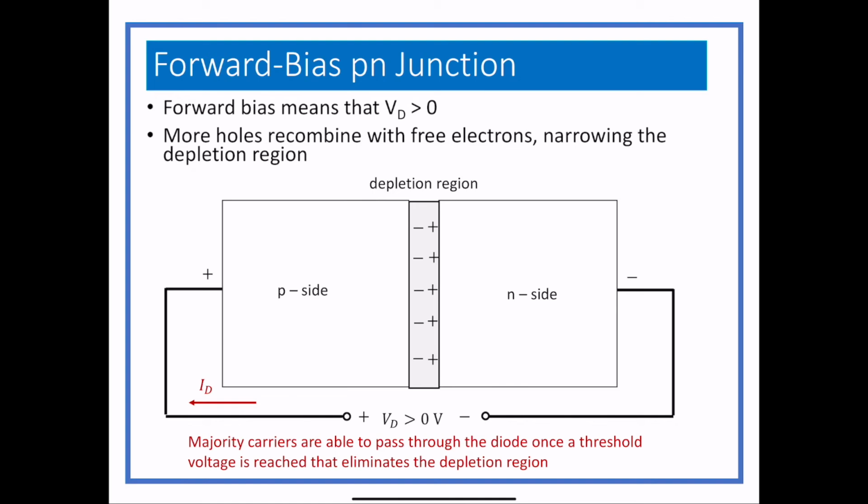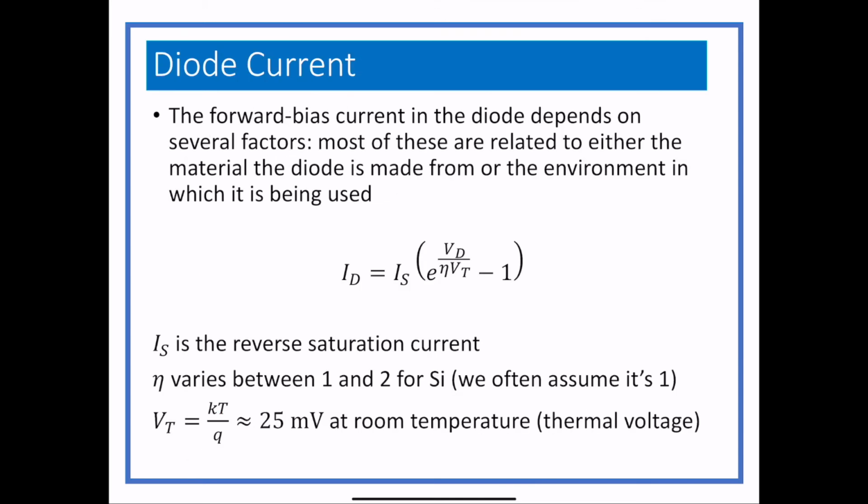So those are the two ways that you can connect a two-terminal diode device. The way the forward bias current is calculated is not linear. Unlike resistors, capacitors, and inductors, which are linear devices, where there is a linear relationship between the voltage and the current, even if you have to take integrals or derivatives in the case of inductors and capacitors. There's still a linear relationship between the impedance of those and the voltage and the current. With diodes, it is not a linear relationship.